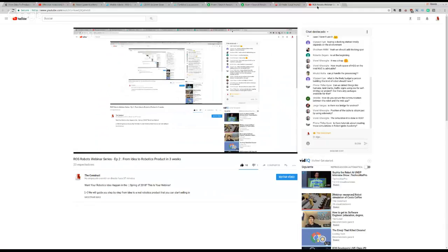Another question: how do you secure the communication between the robot and the web app? Okay, you cannot secure it. You have to have the network closed. At present, ROS doesn't allow security, so you have to be sure that nobody can get into that Wi-Fi network. What we did was that the robot created its own Wi-Fi that nobody else can use, so only the iPad was synchronized with the robot, and that's all. Jorge is asking, is there a ROS bridge for Android? Well, yes.